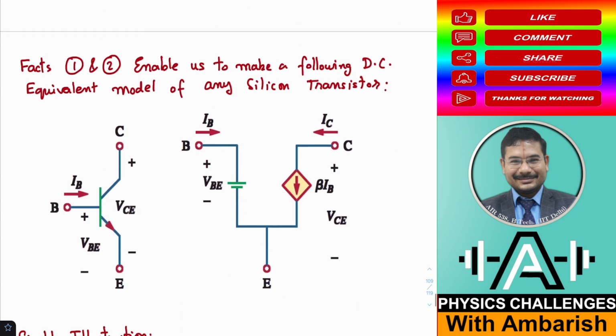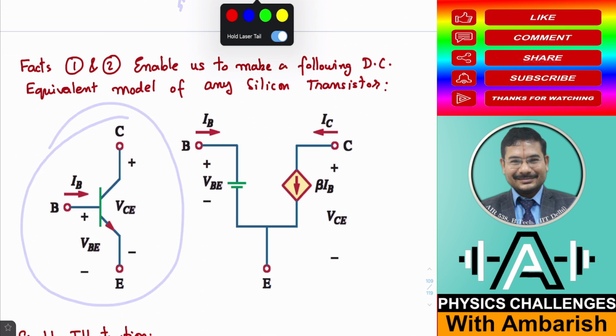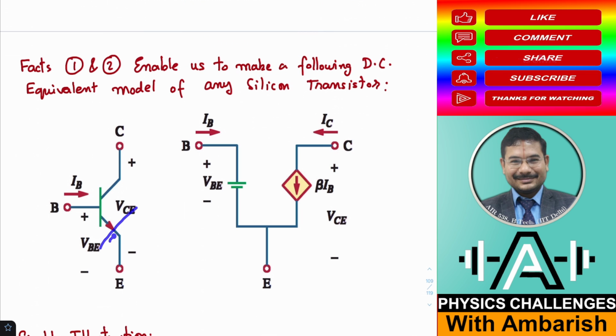So this is my transistor, let us say. Here, at the base emitter junction, you can imagine that there is a battery of 0.7 volts against the emitter current. This arrow represents the direction of emitter current, and there is a reverse battery of 0.7 volts. Why that is there, I have not yet told; I'll tell it later on, when we discuss the why of things. Right now we are discussing just the how of things.